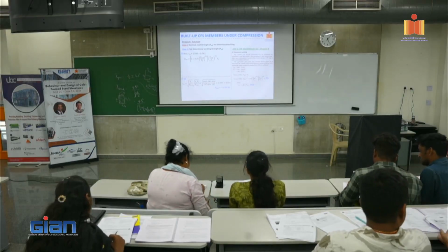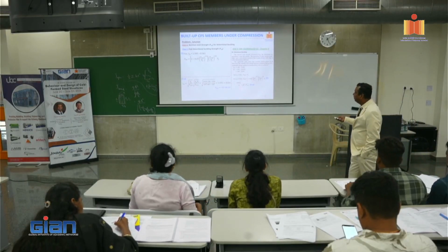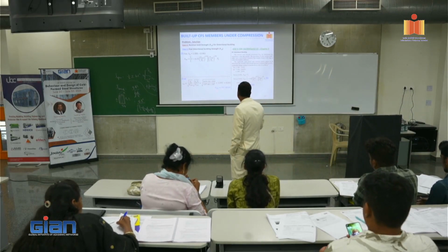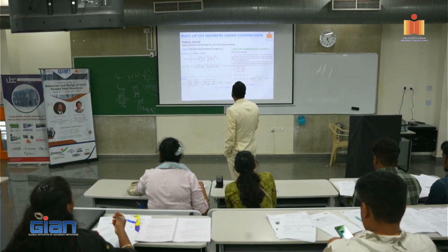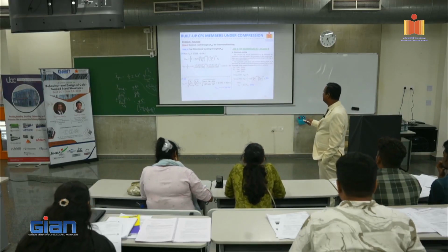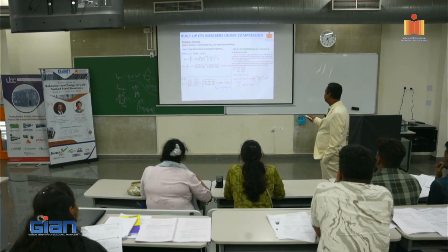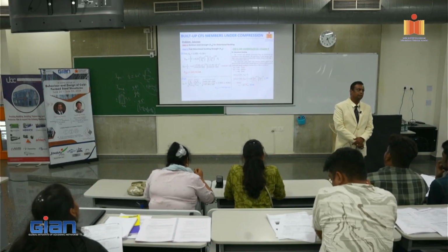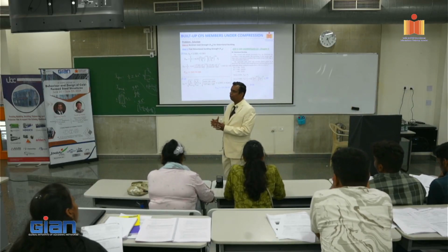Let me solve this. So now we got Py by PCRD, right? So we have calculated PCRD. We got this equation. We are going to this equation. So we have 1 minus 0.25 into PCRD, which is 197.48, divided by 1434.18. We do all this stuff. 245.92 kilonewton. So the third portion is also done.